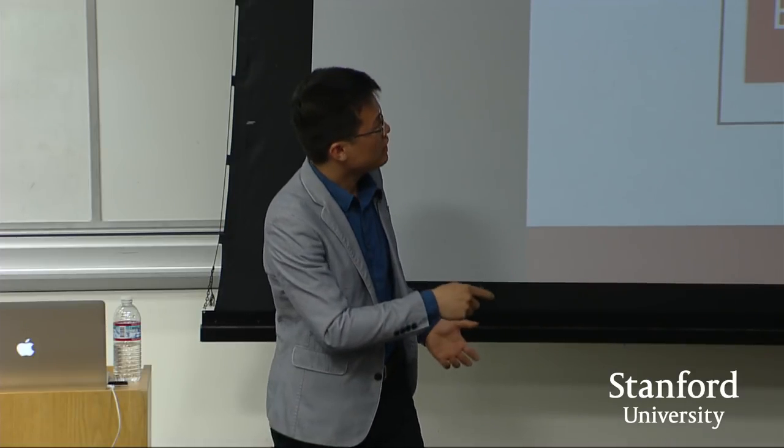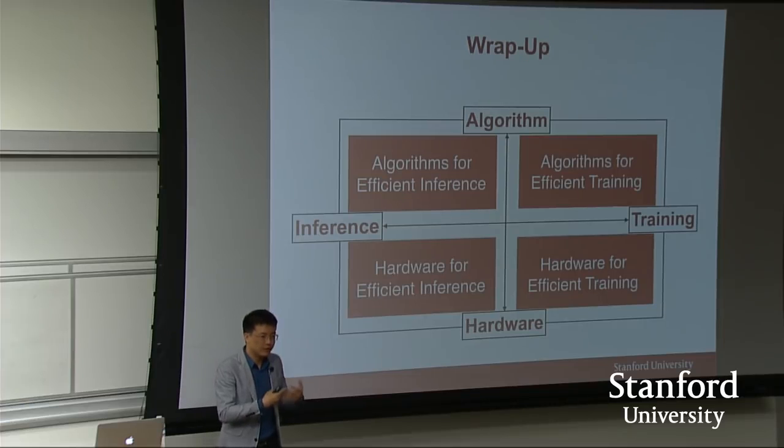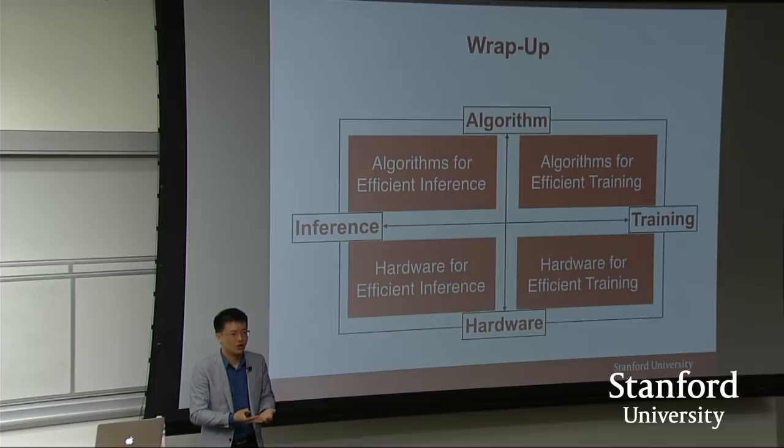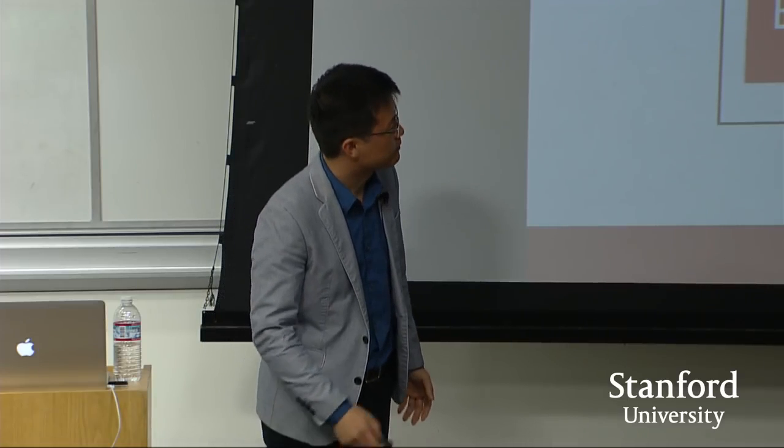And also the efficient algorithms for training, for example how we do parallelization, and the most recent research on how we use mixed precision training by taking advantage of FP16 rather than FP32 to do training, which is four times saving in energy and four times saving in area, and doesn't quite sacrifice the accuracy you get from the training.